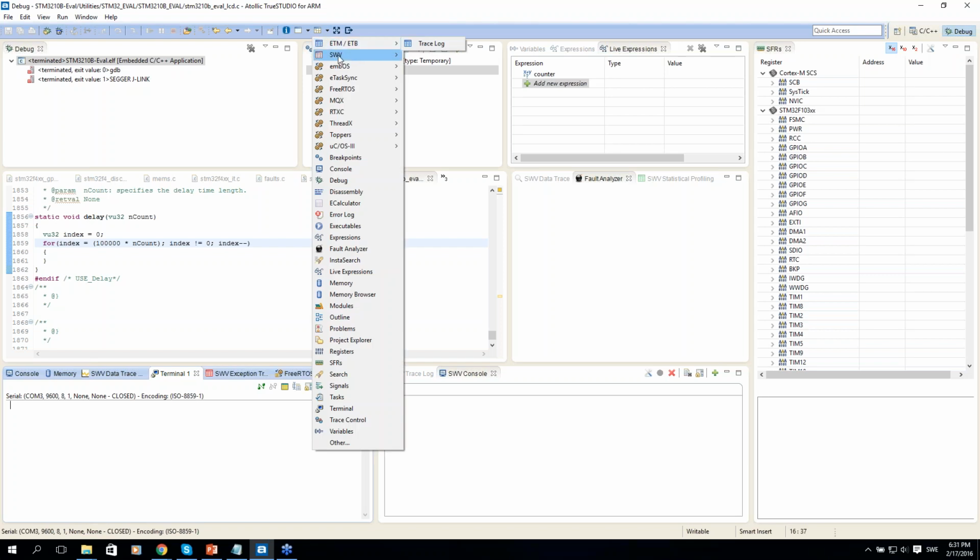So the tracing we looked at today was serial wire viewer tracing. It's an event-based type of tracing. It's the cheap version, which gets you quite far. It's in all Cortex M3, M4, and M7, mandatory by design. ETM tracing instead is real instruction tracing. We support that with the Segger J-Trace or with any probe if the target has an embedded trace buffer implemented.